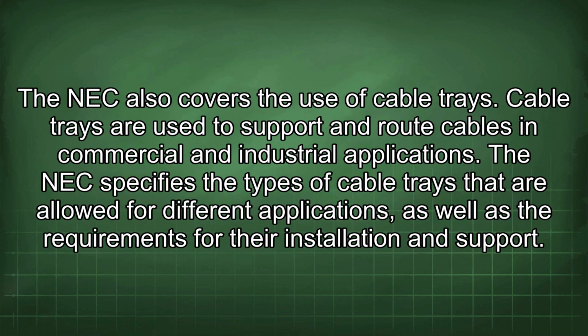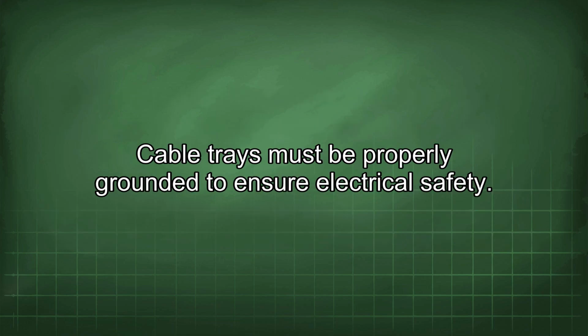The NEC also covers the use of cable trays. Cable trays are used to support and route cables in commercial and industrial applications. The NEC specifies the types of cable trays that are allowed for different applications, as well as the requirements for their installation and support. Cable trays must be properly grounded to ensure electrical safety.